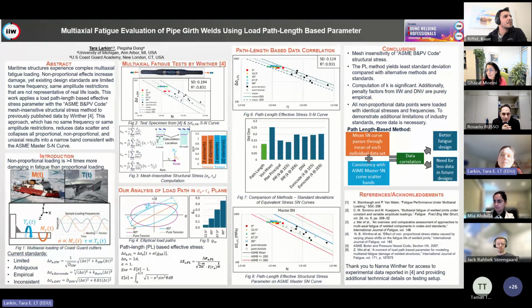So we factor those failures really in the data from the SN curve as opposed to in the models themselves, just because our welds tend to get inspected. So yeah, we factor those kind of failures into the SN curve data as opposed to the actual models.